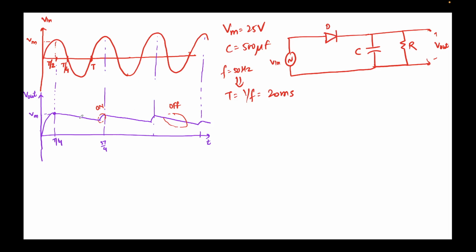Okay, so this is the V out that we have over here. Let's write the expression for VD. So this is what I'm denoting as VD, right? So I can write VD is equal to V in minus V out, right? V in we know is Vm sine omega t, where omega is nothing but 2 pi f, frequency is known, minus V out, we'll assume it to be a constant, in this case Vm. Note, this is the V out, and we ignore the ripple voltage for now. So now this is the diode voltage, right? And we need to find the peak reverse voltage, right? So what is the minimum VD can go? This will be minimized when sine omega t is minimized, right? So VD is,